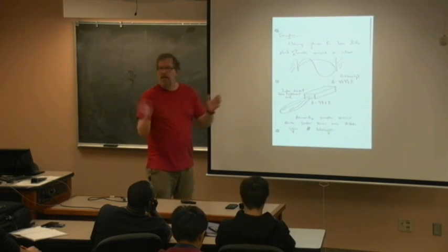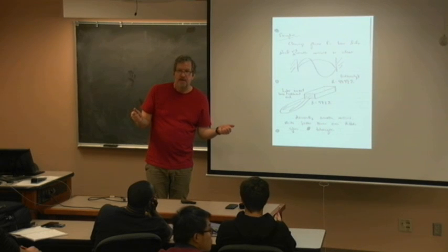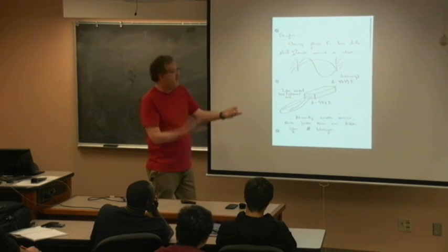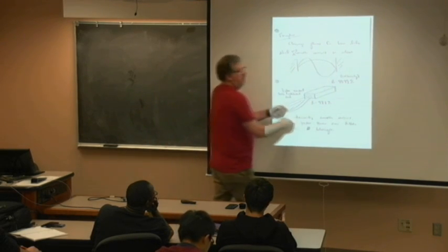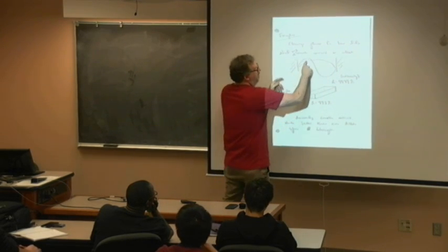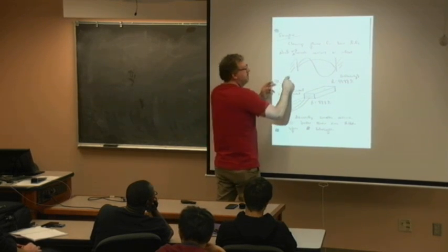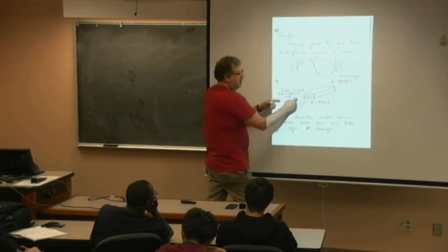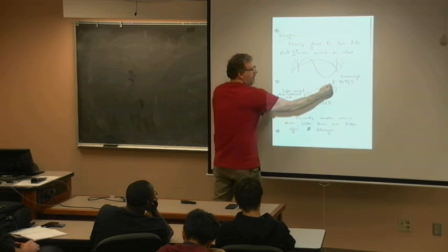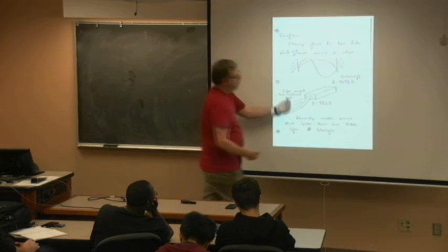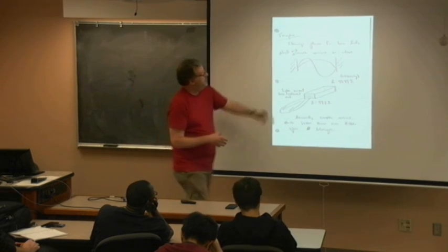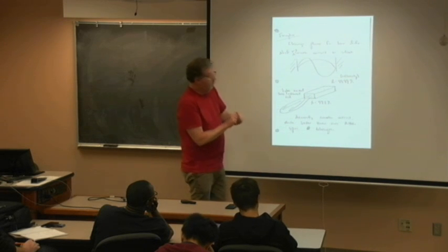Well, it's basically, how many of you are musicians? None of you? One of you. Okay. Well, it's just like plucking a guitar string or a violin, right? Or taking a jump rope and tying it to two brick walls, right? And so I have a fundamental frequency, and I have a first harmonic, and so forth. Well, the same thing goes that I can count an integer number of wavelengths of light that go through that cavity. And so if I have two reflective mirrors, this forms a Fabry-Perot etalon and forms the laser diode. But it's formed by the fact that I had perfect crystallography.